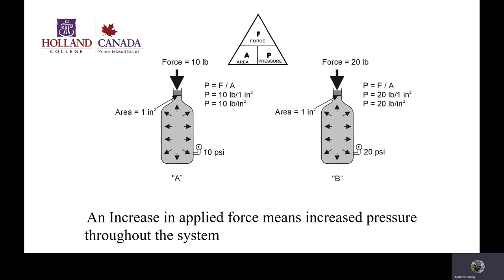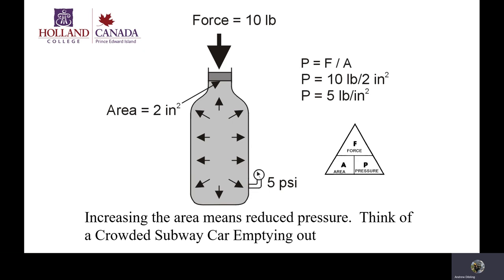Hydraulic systems can be extremely dangerous because of the high pressures and the toxicity of the fluids. So you always want to take into account safety at all points. That means I don't work on a hydraulic system without gloves on or without safety glasses on, simply because you only have 2 eyes and you only have 2 hands, and they're too easy to lose. If you want to have a long career, it's very important that you take care of your best assets, which is your mind and your body.